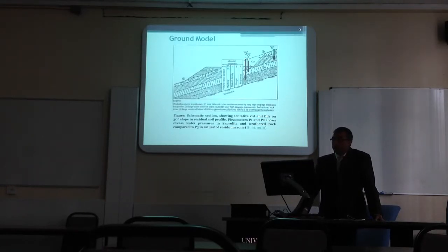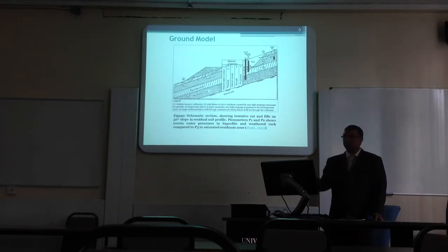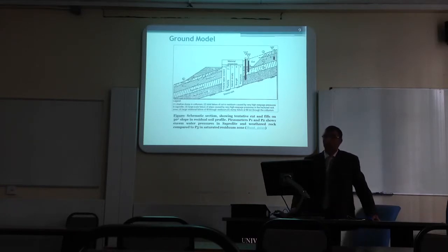This ground model basically depicts the main features of embankment construction, how the embankment is going to be constructed. So you can see the shed of slump colluvium can be detected if you make this model. This model is going to be made by the GI work, whatsoever you have done at site. You can know the seepage forces, you can know the piezometer installation and the water level from the piezometer installation, and of course the C and phi for material property, which is required for design.